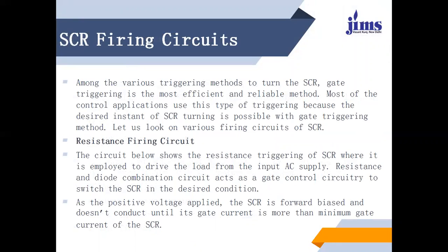In the case of the SCR firing circuit, we are discussing various triggering methods to turn on the SCR. Gate triggering is the most efficient and reliable method. Most control applications use this type of triggering because the desired instant of SCR turn-on is possible with the gate triggering method. Let us look at various firing circuits of the SCR.